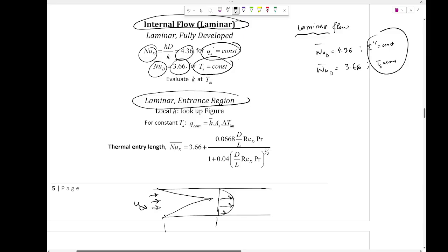And that steam was slowly getting droplets. At some point, by some mechanism I'm not explaining, there was this entrance zone. So I had to take care of the setup and the flow in such a way that the entrance zone effect is minimal. Does it make sense? The entrance zone is so important because it has a different heat transfer rate. The fully developed zone has a different heat transfer rate.